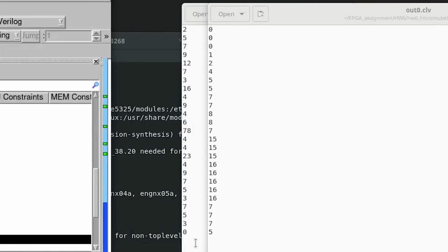But we'll have to consider one more process in RTL verification, that is, it follows something called verification of golden output to generated output. Golden output is basically the output generated by the software simulator during software simulation. So in one cycle where we provide an input, it will generate the output and verify if that output is the same as the golden output.